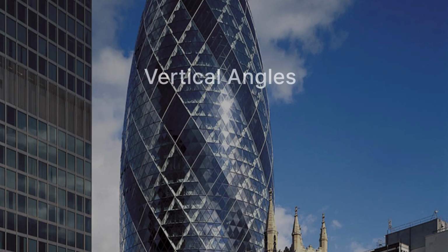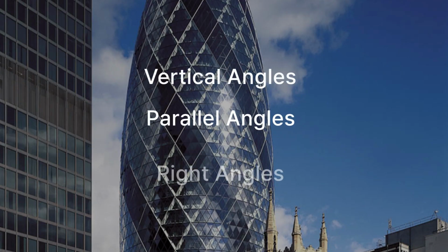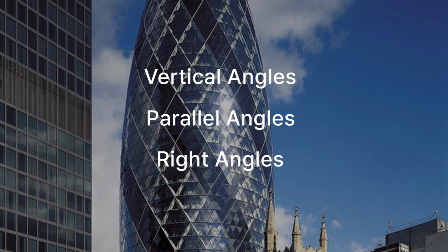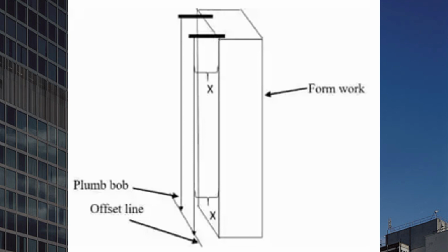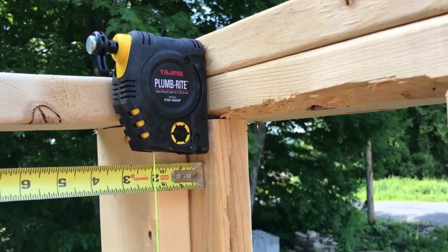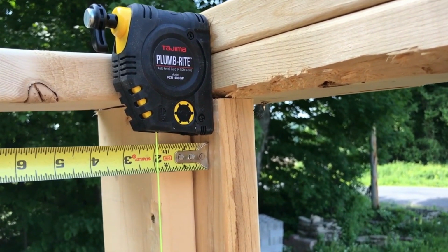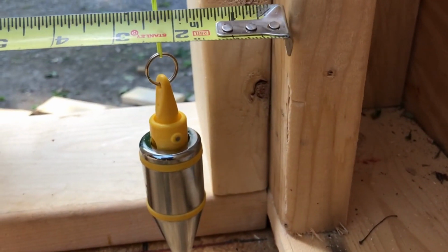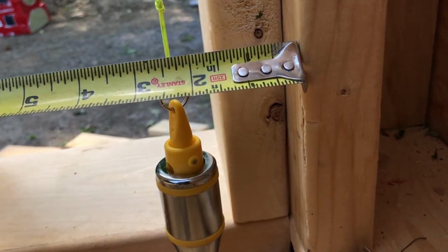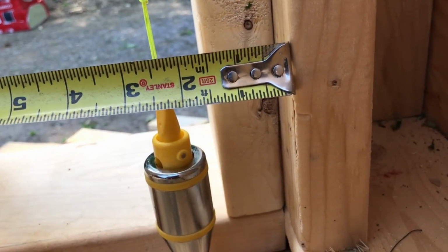Errors in vertical, parallel, and right angles that may occur during construction should be measured. Usually, the error is measured using a plumb bob to easily see whether the diagrid members are erected vertically or not. After attaching a thread to a weight or plumb, check whether the node is constructed at the desired vertical angle through the guideline on the floor.